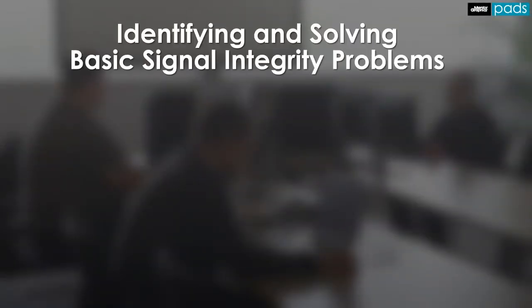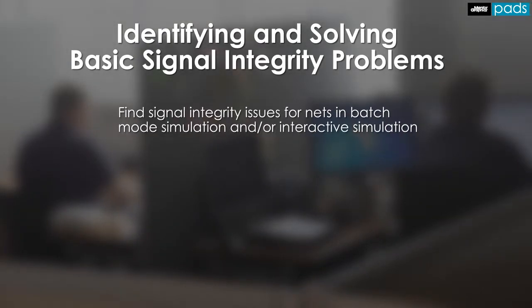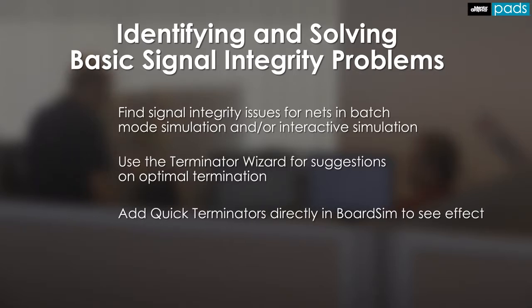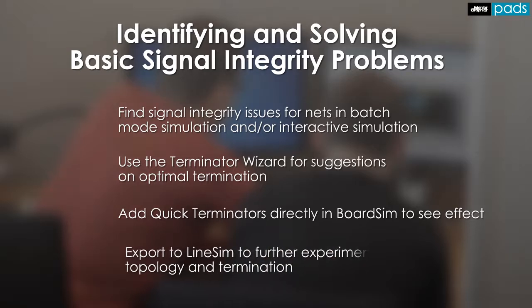Signal integrity problems on the PCB can easily be located and fixed using HyperLynx. After exporting your design, you can run simulations either in batch mode or interactive mode to identify any potential signal integrity issues. The built-in terminator wizard can analyze the topology and suggest the optimal termination. And you can then see that terminator in action directly in BoardSim using the quick terminators function.